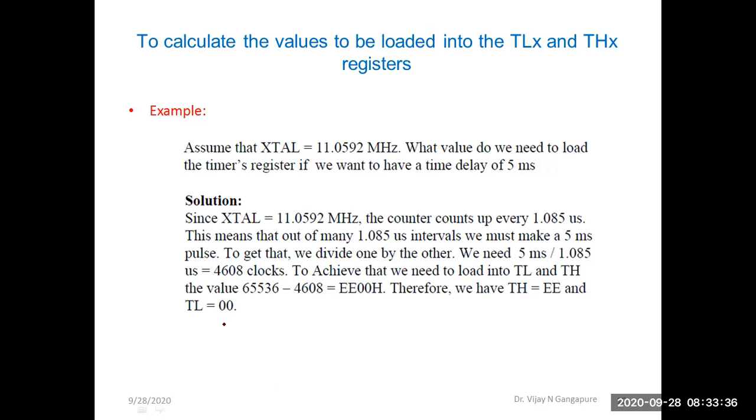Okay, so in step 1, the time delay given is 5 millisecond. Okay, 5 millisecond. So in step 1 I will divide this 5 millisecond by 1.085 microsecond.